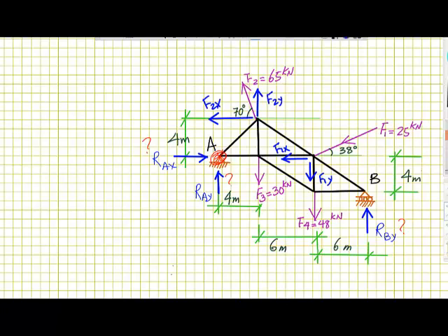Now that we have resolved the forces, the value for these forces is something we covered in the previous lecture. For F1, if I do this, then this angle will be the same as 38. The 70 for F2 is already clear, it is straightforward, so I don't need to do any clarification for that part. I will just go ahead and do the values for F1x.